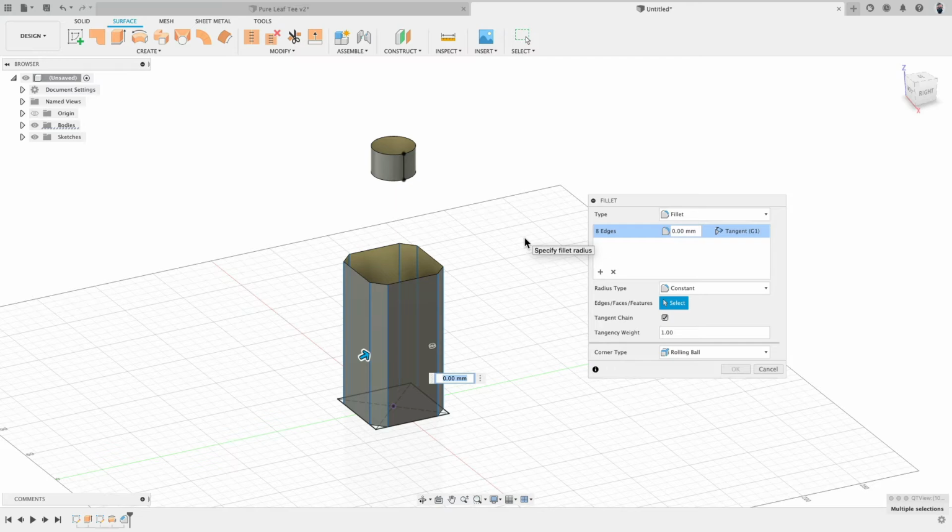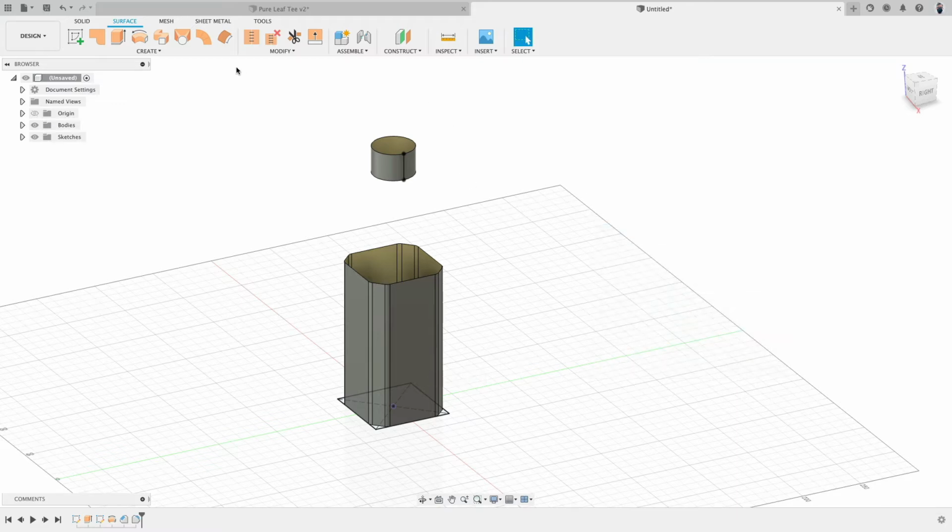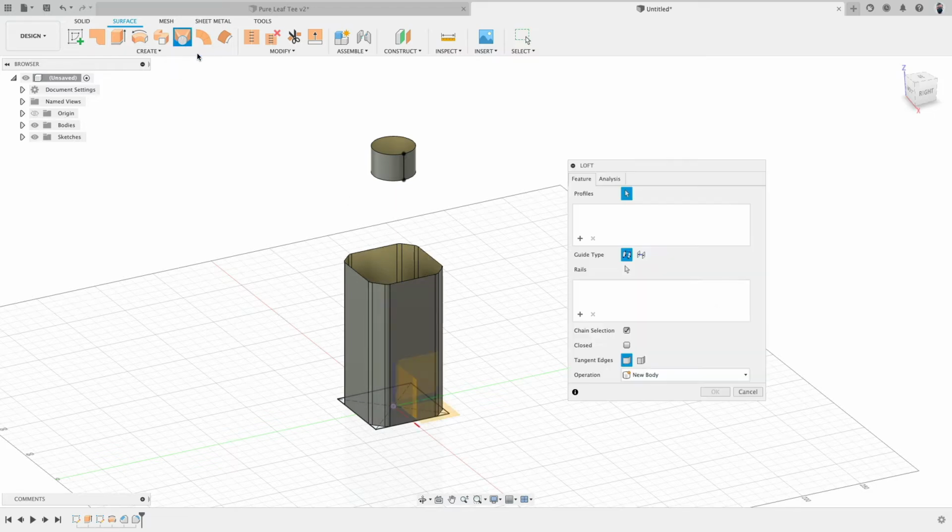Very good. Now you select them one by one. 4 millimeters, let's say 5 millimeters. That is very good. Currently, we just keep it on G1. Again, I keep this on G1 because it's faster. At the end, I will switch this to G2. Very nice. Okay, so now we actually have nicer rounded corners and then flat sides.